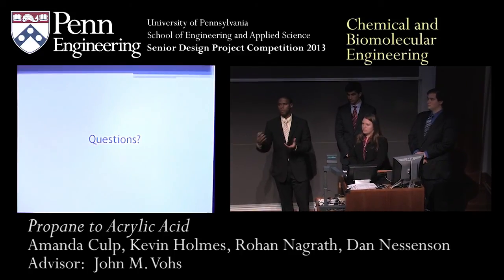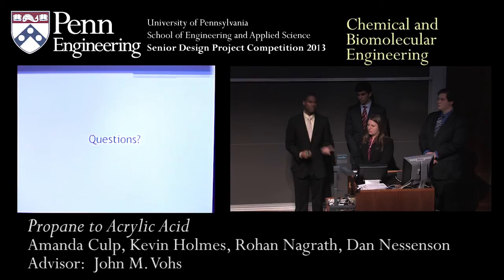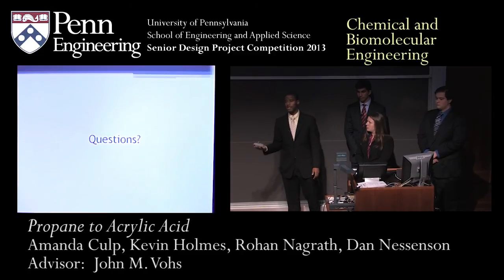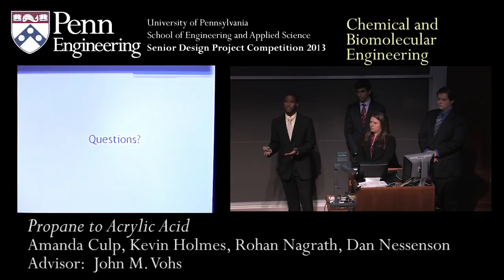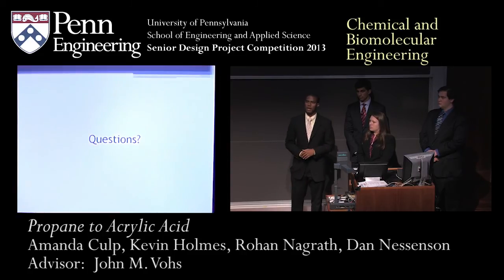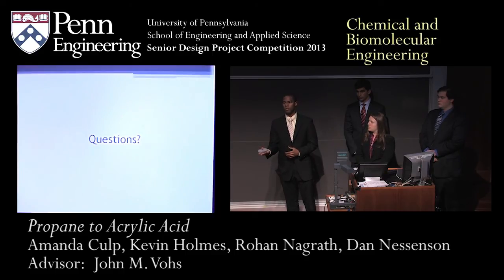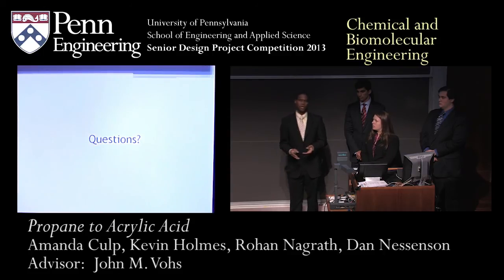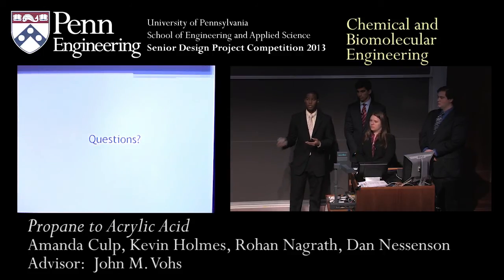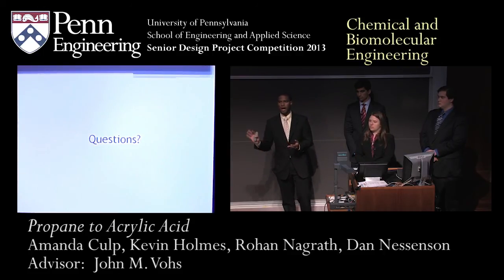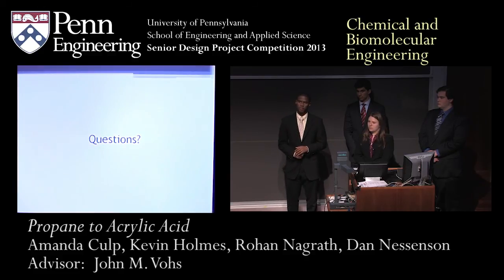containment unit around the reactor, usually probably made of concrete. In addition, since most of the process is in gas phase, we've costed having leak detection systems throughout the process as well. And I think all that combined would take into account a lot of the safety problems we have. To your point though, I mentioned the upper flammability of propane and oxygen. It's about 1-to-1, but our most oxygen-rich stream has about 5% oxygen and 20% propane. So we're well beyond any sort of exposure that might occur from that aspect.